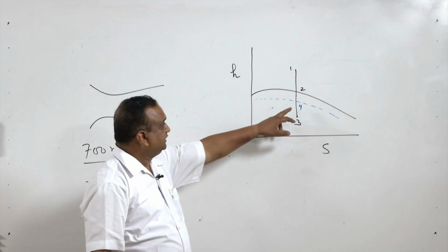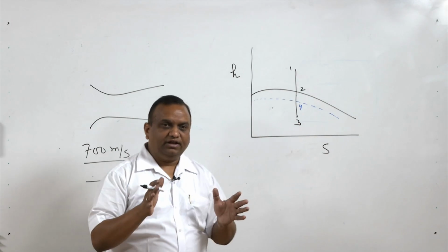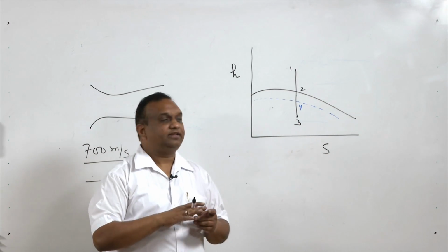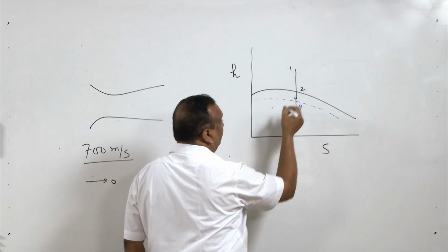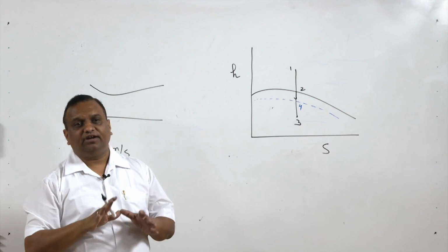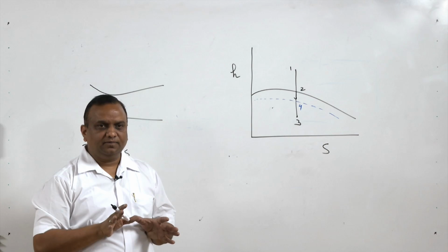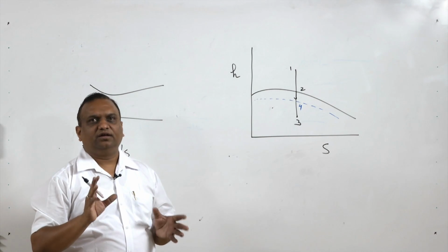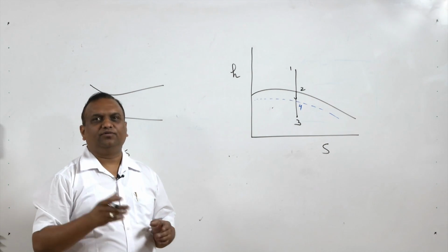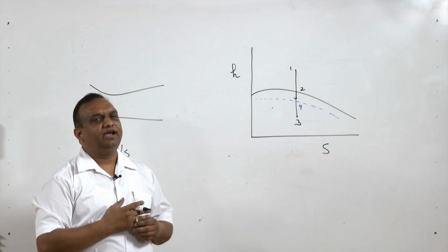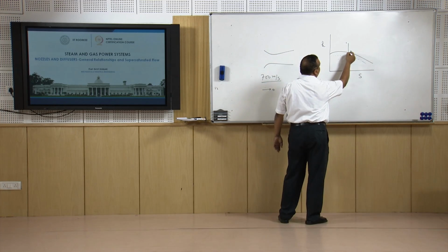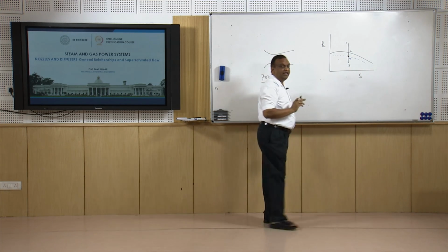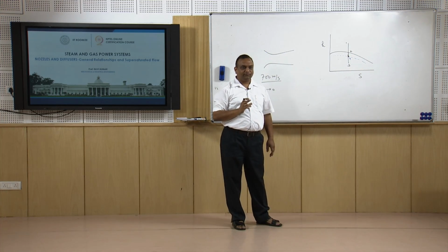Initially condensation does not occur, but because the state is continuously changing, condensation takes place without any nucleation site when the density of the fluid is almost 8 times the density of the saturated vapor. So while expanding from this point to this point, condensation will initiate at this point. This lag is known as supersaturated flow of the fluid.